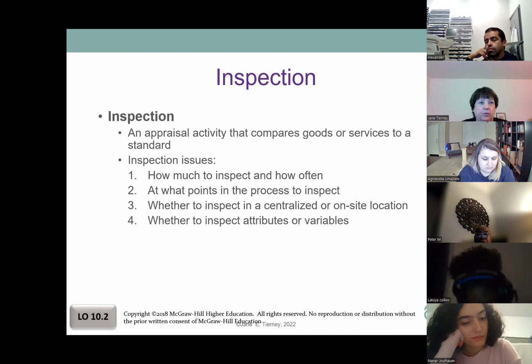So we have to decide when we're going to inspect things. And there's some natural kinds of things, and I'm using a house rather than a production process, but you can think about what you might need. So if you're going to cover something up, you want to inspect it before you cover it up. If you're going to join something like pouring the foundation, you're going to check it before you're going to let the foundation set up and make sure it's done correctly.